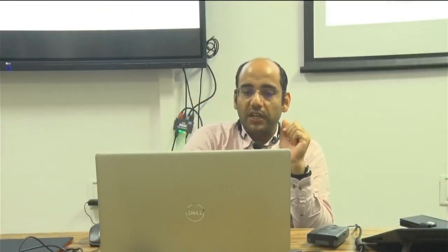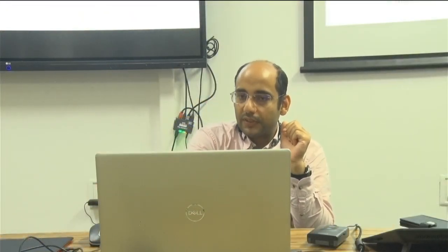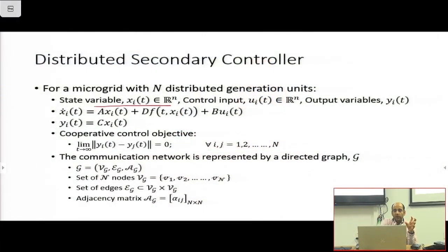That means, for example, frequency error omega1 minus omega2, power sharing error m1p1 minus m2p2, or reactive power sharing n1q1 minus n2q2. All of these individual errors should go to 0. If so happens, that means omega1 is equal to omega2, m1p1 equal to m2p2, n1q1 equal to n2q2. That means your objectives are met. So our objective is to achieve this. At steady state, the norm of yi(t) minus yj(t) should be equal to 0.